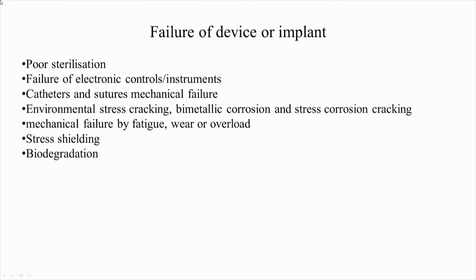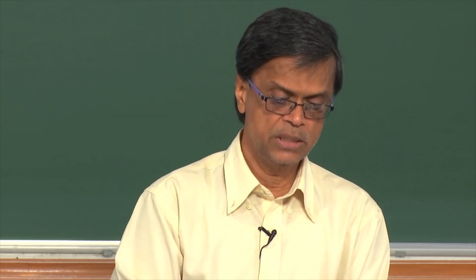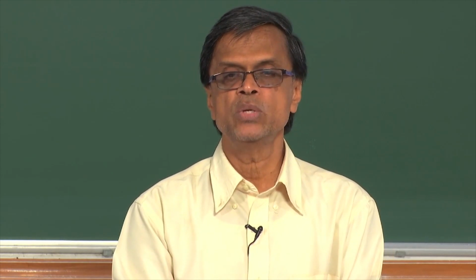Biodegradation. So if you have polymers, they may start degrading because we have enzymes like lipase and esterase inside the body, which may slowly degrade them. Of course we have oxygen also, so there could be oxidation taking place, so polymeric material may start degrading, so that is an issue. Once it starts slowly degrading, you may lose its mechanical strength, it may lose other properties.